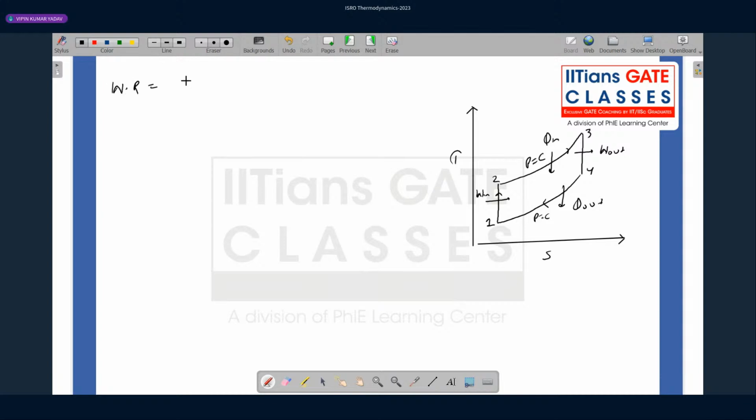Okay. Now, what is work ratio? Work ratio is defined as net work by turbine work. Now, what is net work? Turbine work minus compressor work, by turbine work. So I can also write 1 minus work of compression by work of turbine. Okay. So what is work of compression? By seeing this TS diagram, you can tell me.